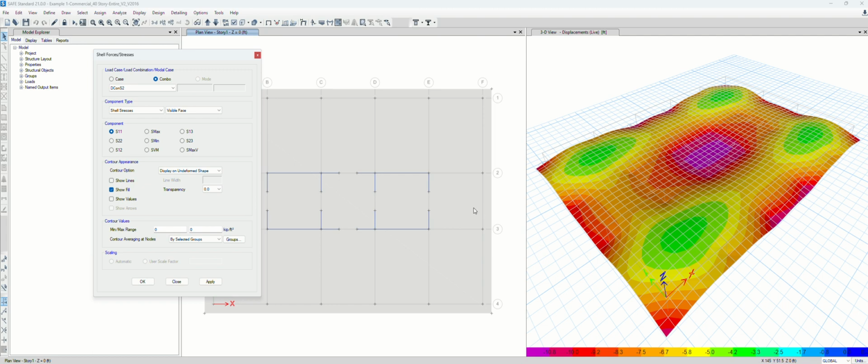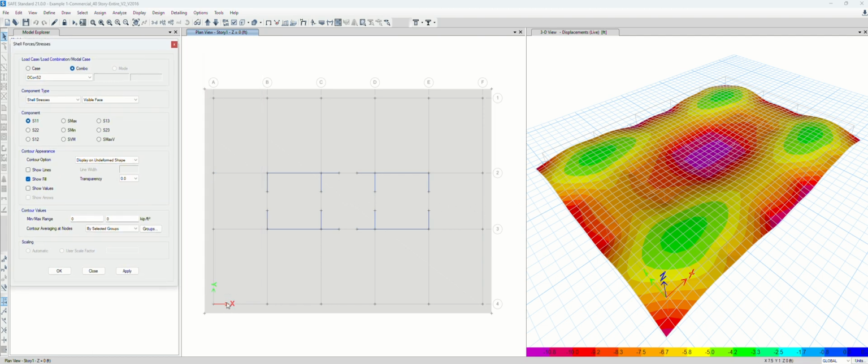One is the plane XY. See that? Red is local axis 1 and also global axis 1. They are matching, right? Y is global Y, but also local Y. So vertical is vertical 3. So we are checking the vertical shear, right? Something similar to the beam design. So I'm going to turn this on and see.